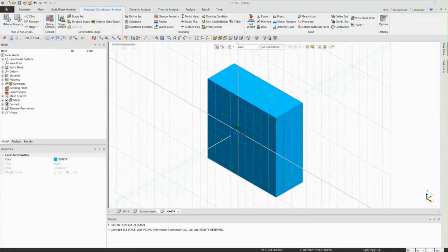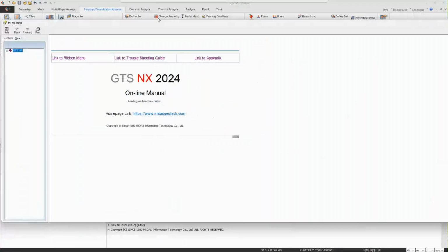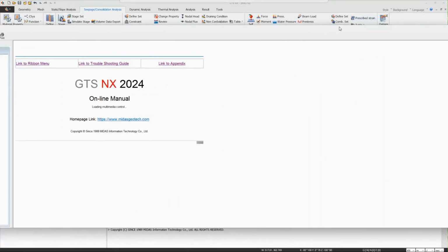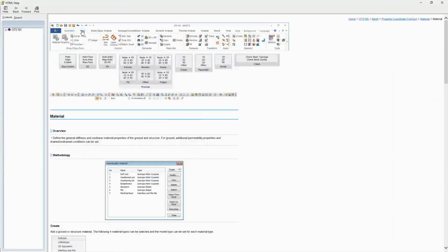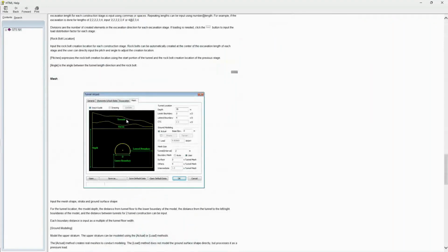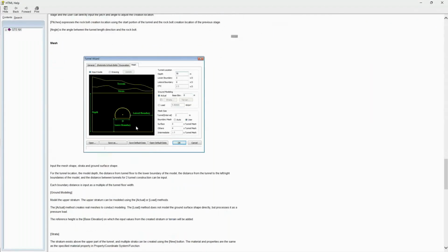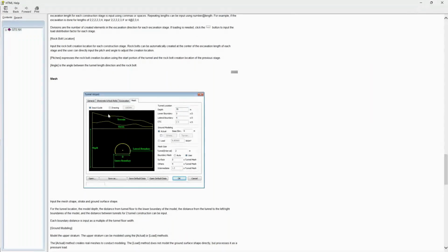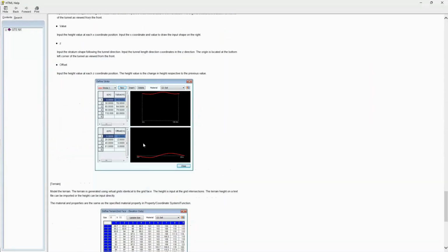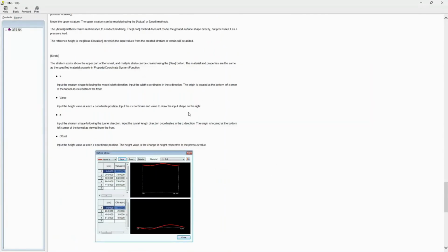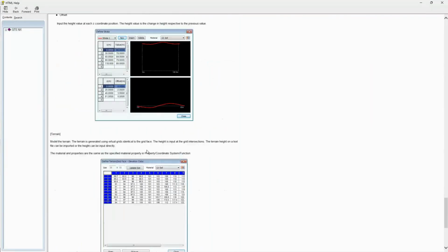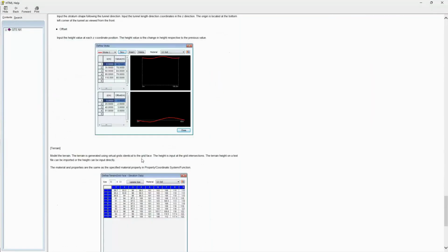I'll just mention it here. We can do it here. Suppose, we can actually capture this kind of actual terrain surface. In this case, we do not need to put the overburden pressure separately. We can create that geometry using this elevation data. In both the X and Y extent, this actual terrain or strata surface will be automatically created.